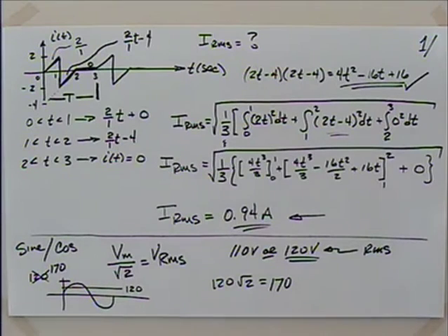Okay. This is why when we first sat down to the oscilloscopes at the end of last term and you grabbed your digital voltmeter that you were used to and put it on the circuit and compared it with what you were seeing on the oscilloscope, they didn't work out, because most digital voltmeters are going to be measuring RMS. Okay? And your oscilloscope is measuring the wave itself, right?